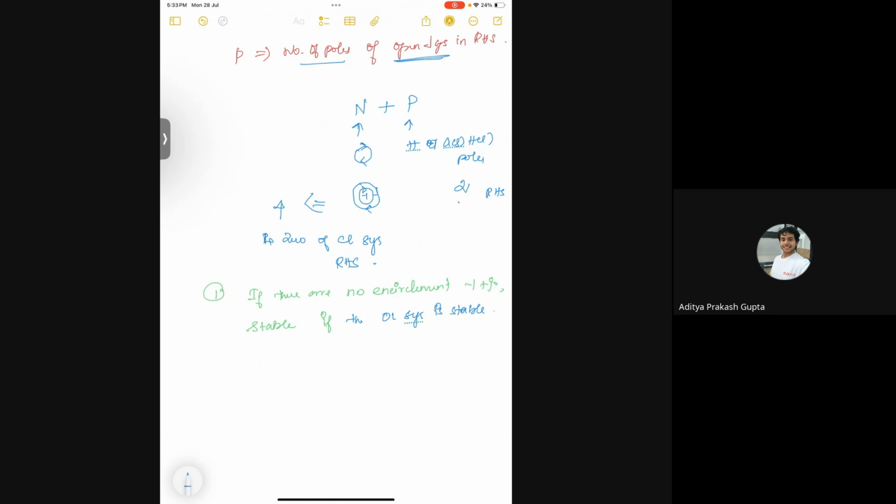So in my Nyquist plot, for example, there is no encirclement around -1. So here, I can conclude that my closed loop system is stable provided my open loop system is also stable. Because sometimes the open loop system can have unstable poles, but when you convert it to the closed loop transfer function, it becomes stable. The other way is also possible. When the open loop is stable, the closed loop system might be unstable based on the gain value and feedback.